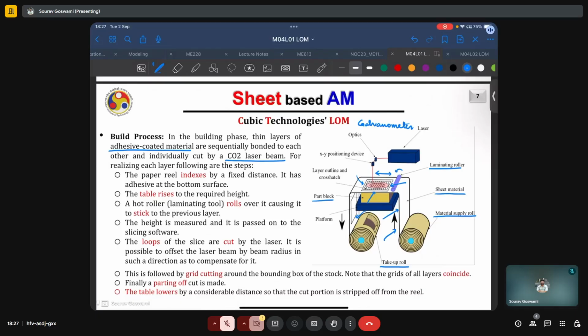We have also discussed how the wavelength of the energy source is a very important parameter in deciding its interaction with a given material. Certain wavelengths may be suitable for metals, whereas others may be suitable for ceramics. CO2 lasers, in fact, are also suitable for ceramics, apart from paper. And even in the case of metals, the absorptivity of the irradiation source itself may vary with wavelength.